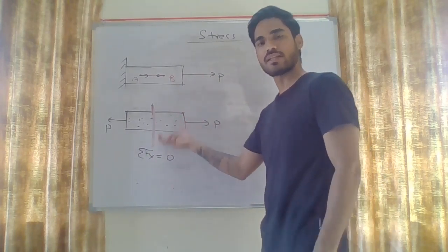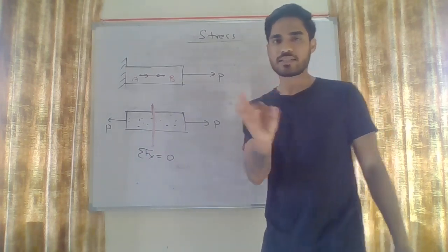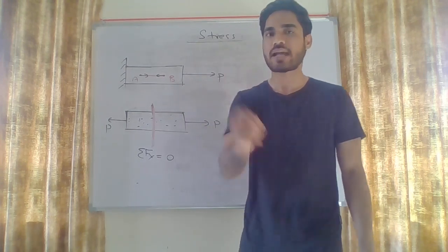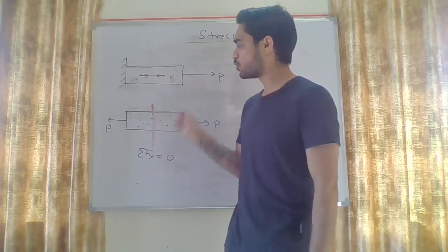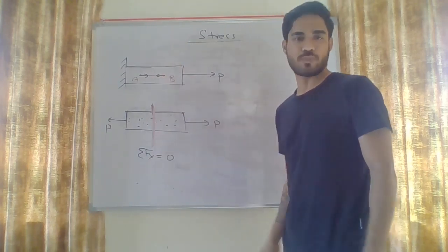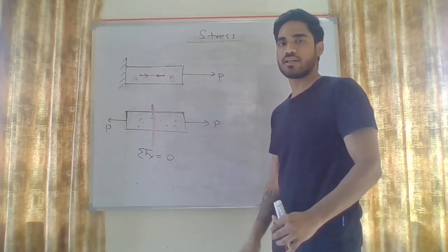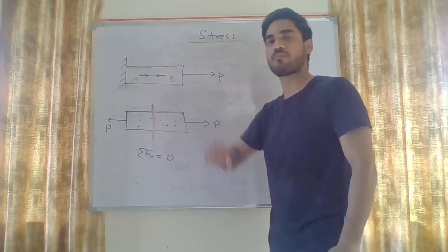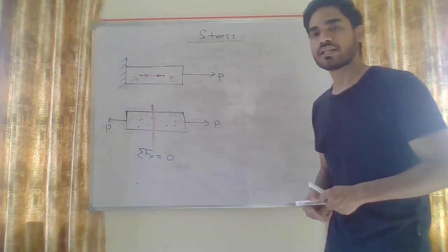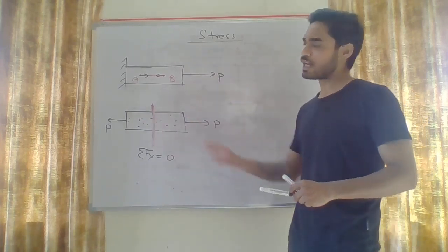We want to find the stress, and in order to find stress, first we need to find the internal force on this plane. So what we will do, listen to me very carefully, because this is the basic concept of stress. In the entire strength of materials, whenever I say find the stress on this plane, you have to do the same thing. If you want to find the stress on this plane, you will cut the body from this plane, because we want to find internal forces, what is happening inside the body. Until and unless we expose the inside of the body, we can't find the internal force. So I will cut this body from this plane, and I will draw the free body diagram of either the left part or the right part.